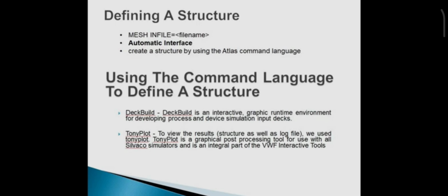Using the command language to define a structure, you must know about DeckBuild and TonyPlot. What is DeckBuild? DeckBuild is an interactive graphical runtime environment for developing process and device simulation input decks. The second one is TonyPlot. TonyPlot is used to view the results. We use TonyPlot to show the results of the structure as well as the log file. We can see these only in TonyPlot. TonyPlot is a graphical post-processing tool for use with all Silvaco simulators and is an integral part of the VWF interactive tools. VWF is Virtual Wafer Fab. Next slide please.